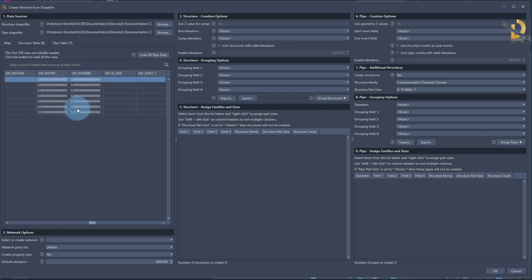Not all the paths do have information. Those paths have a 0 elevation, so that might also be a problem. So this is not a great shapefile, but that's what you get sometimes, that not all the information is here. So you're trying to recreate the services, but you have no information or not enough information. But at least we get a geometry. And when it comes to vertical adjustments, we can do it manually later on, or we can just use the values that are there.